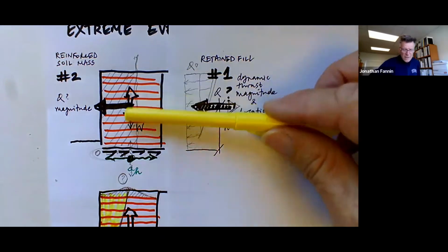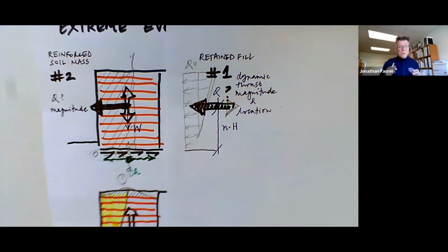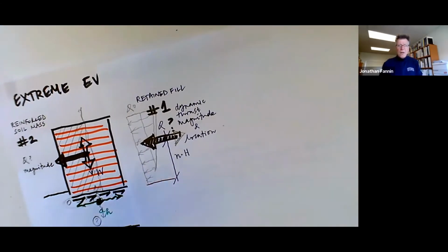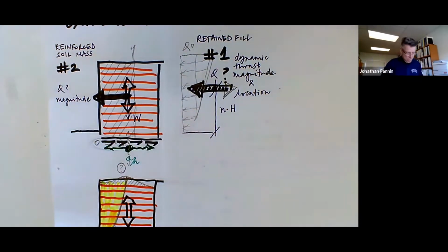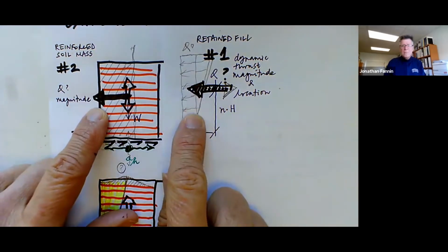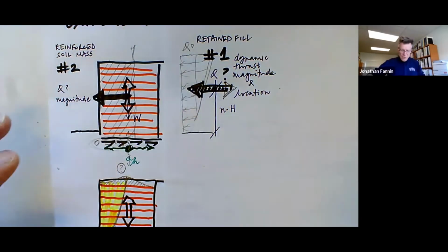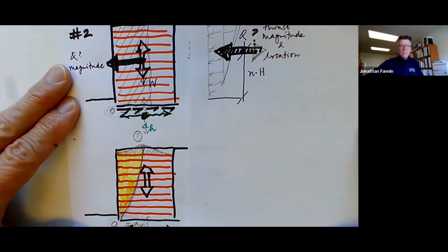Let's work on the basis that the fill zone is a good quality backfill soil, well drained, and the issue of excess pore pressures we can ignore for purposes of simplification. So there's the incremental demand, and let's drop down to the internal stability and look for the incremental demand here.